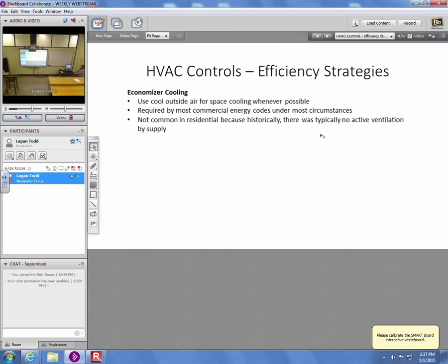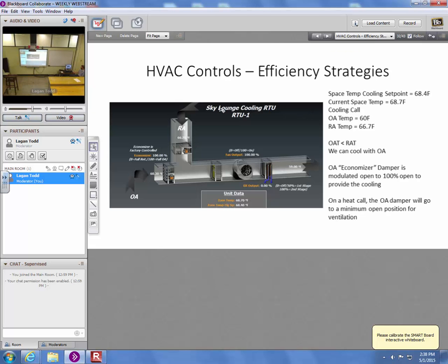Makes sense. There are a lot of furnaces out there that do have AC in them with no outside air, so they can't economize. They're just going to run the AC when there's a call for cooling. You can also have a separate system that does the economizer, just run the fan only. Well, again, a lot of furnaces don't have any outside air ducted into them, so even if you run the fan, you're just recirculating inside air. So there's no potential for that there either.